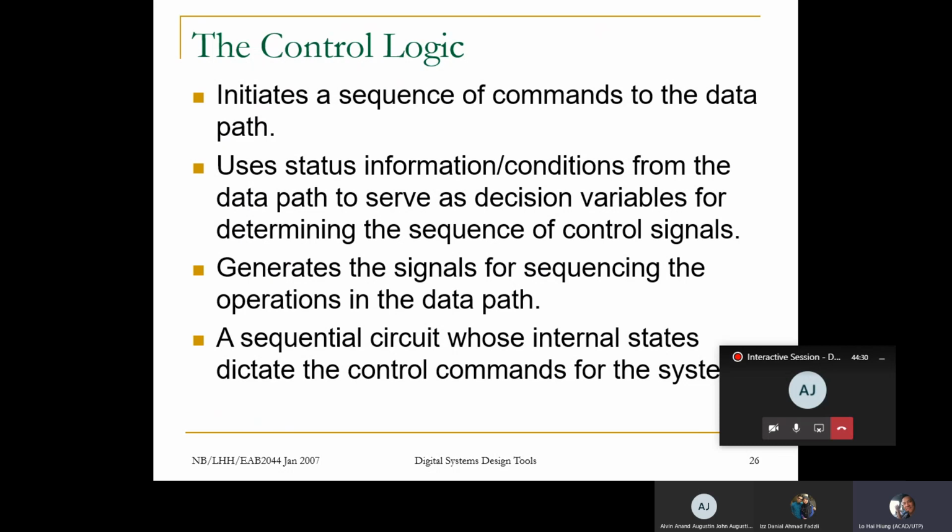The control logic is a complex part where they have to use a graphical diagram to show how you move, because to visualize the timing, when this happened and when do you go to this state, when do you go to this state, is complex. That's why they have to use a graphical tool. So the control logic is described using a graphical tool, the state diagram.